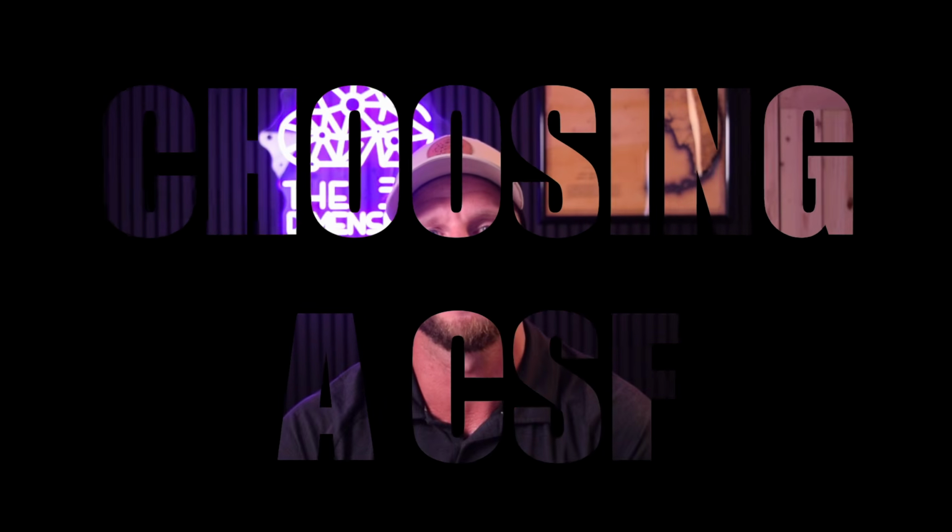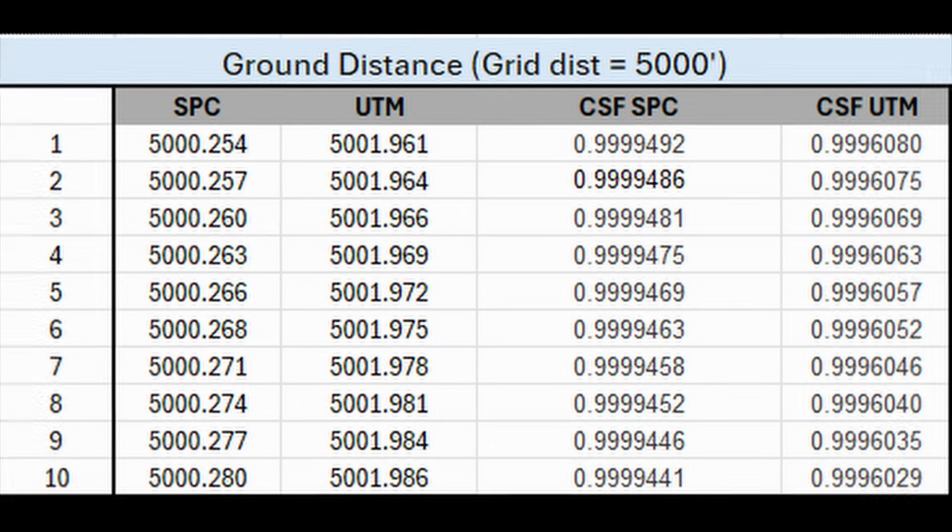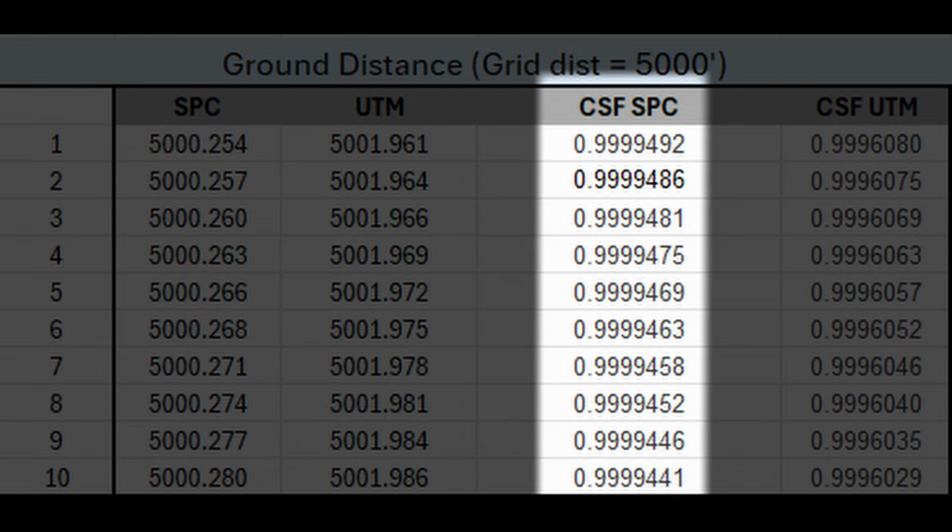We really only want to use the combined scale factor from a single point when we convert a project from grid to ground, and the choice of which point to use to calculate the combined scale factor will affect the distances between every point in the network. As you can see, every point in this example project has a slightly different combined scale factor. So depending on which point we use, and hence which combined scale factor we use, we get slightly different ground